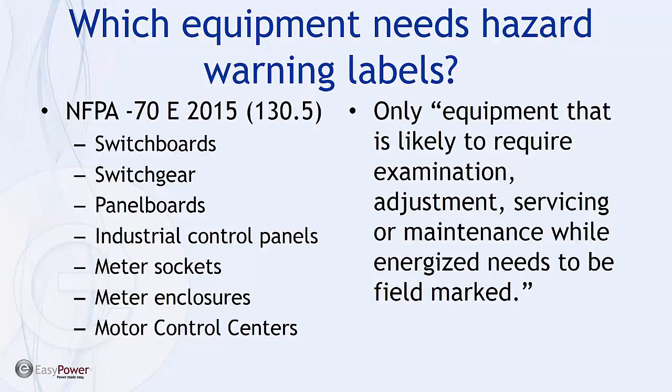For instance, we had a report that at some chemical facilities in Houston, the technicians were taught to regard any piece of switchgear where there could be an interruption of electrical circuit as needing a label on it. If they approached a meter panel or a switchboard that did not have a label, they were to consider the label to have blown off, stop what they were doing, and then go find the remediation and the actual data that should pertain to that particular disconnect. So again, the point is the focus is not the letter of the law, it's making sure that we're improving our workplace safety.